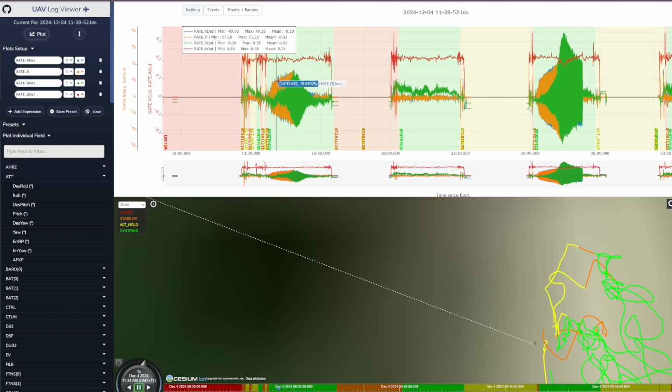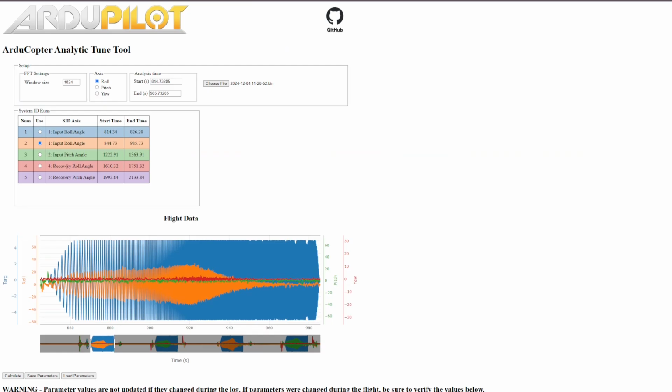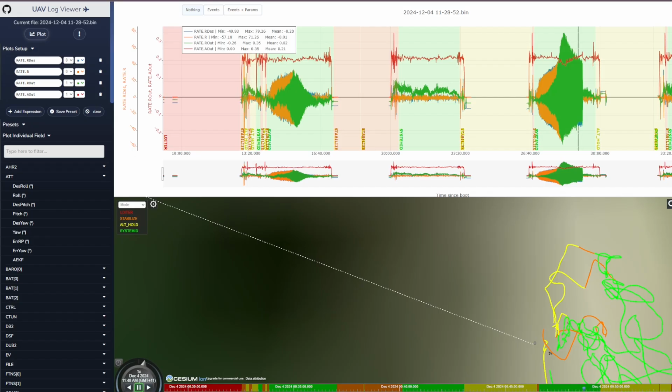So you see down at the lower end it looks reasonably similar, slightly less, but then at the high end the acceleration limiting and all that sort of stuff really limits it. But things like acceleration limits, that sort of stuff, do tend to be nonlinear things, so that too can be non-ideal. My personal preference is to use the recovery roll angle, but to keep the magnitude such that this doesn't happen.